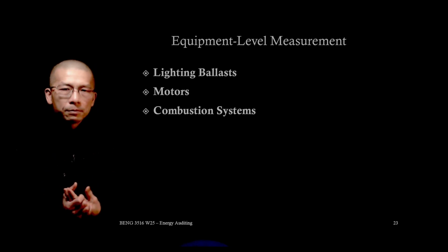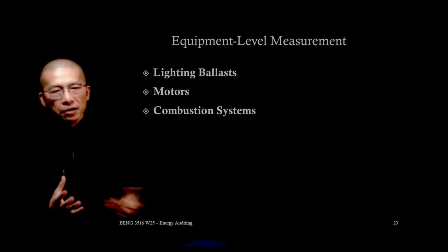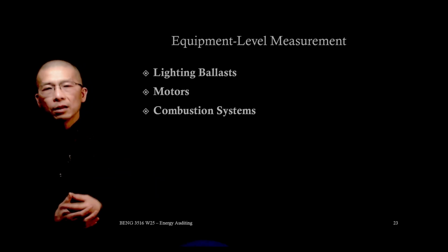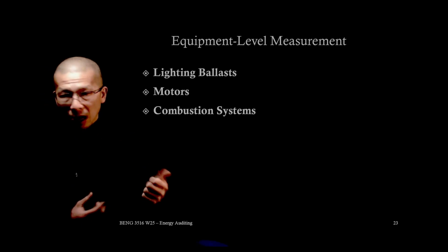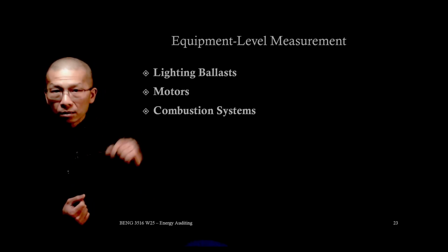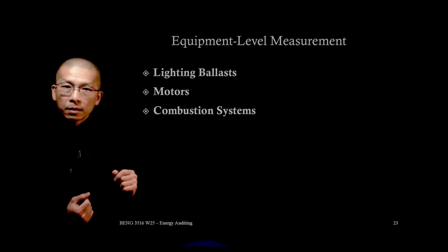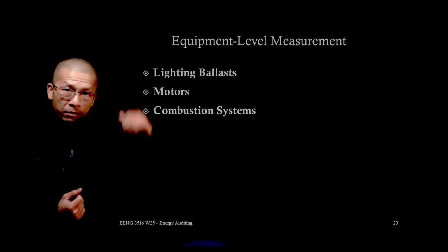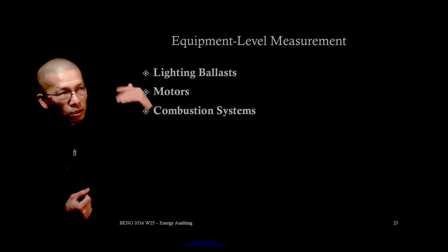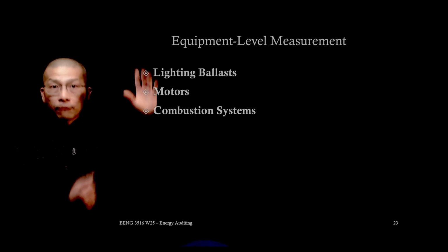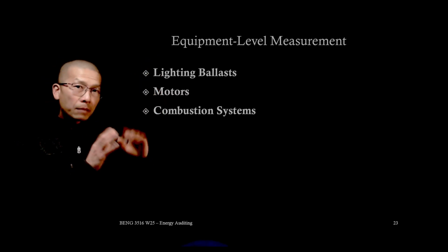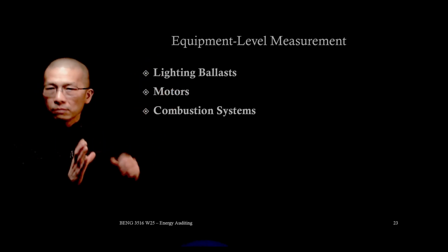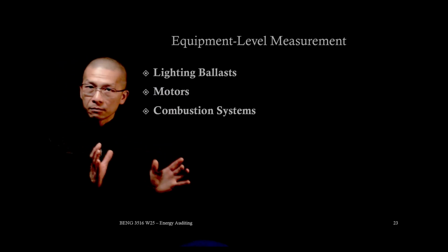Combustion systems such as boilers, furnaces, water heaters, we will want to know the fuel use, how much fuel goes into that equipment. Stack temperature, because that's the temperature of the hot flue gas that goes to exhaust. If we can capture that energy, it's really good.